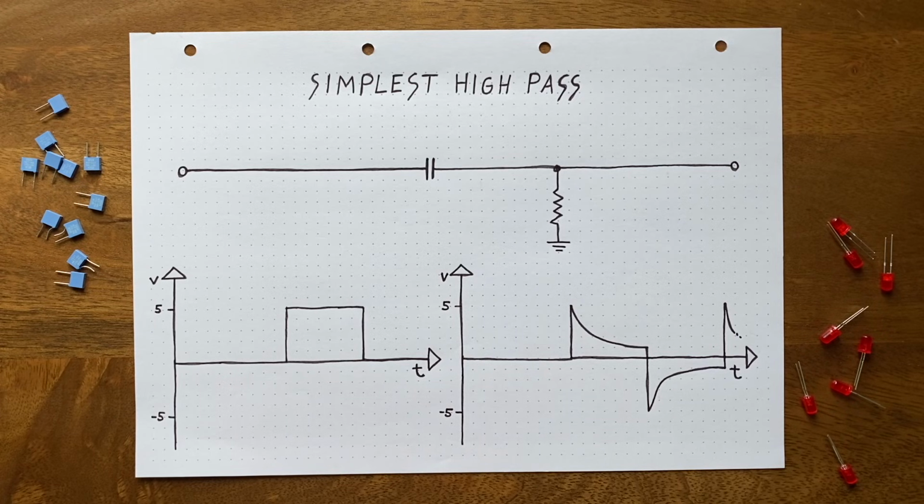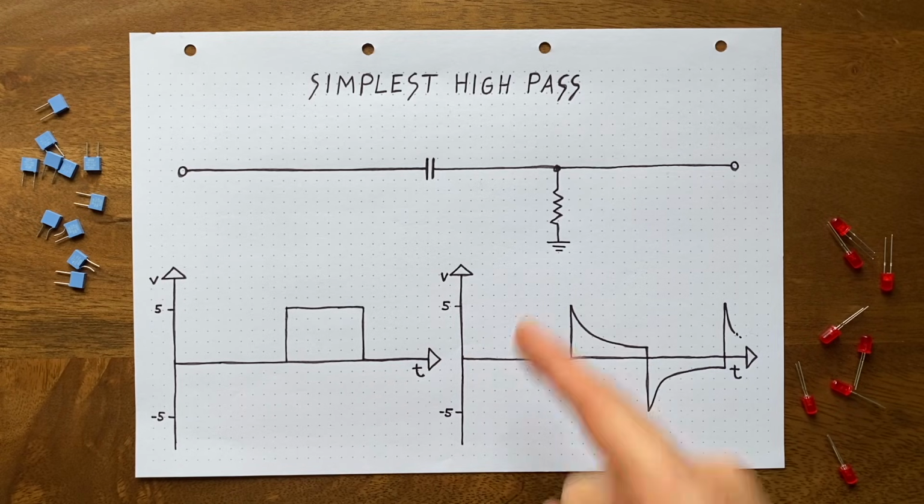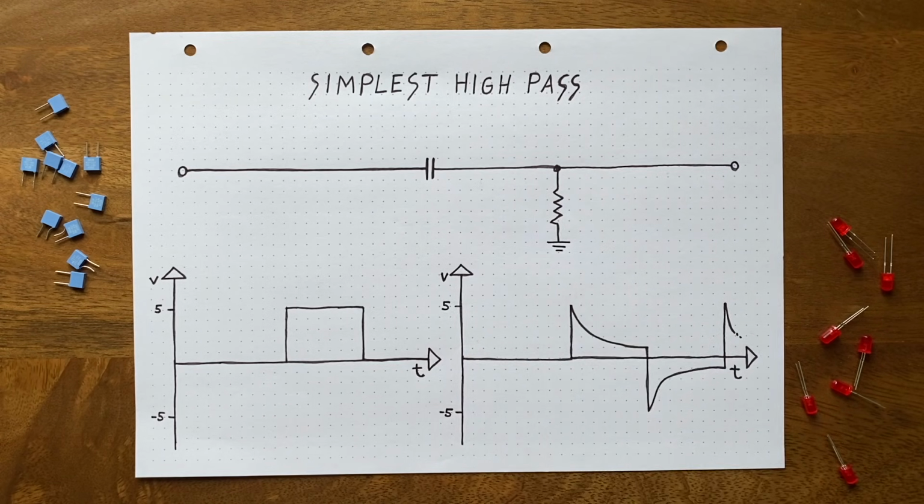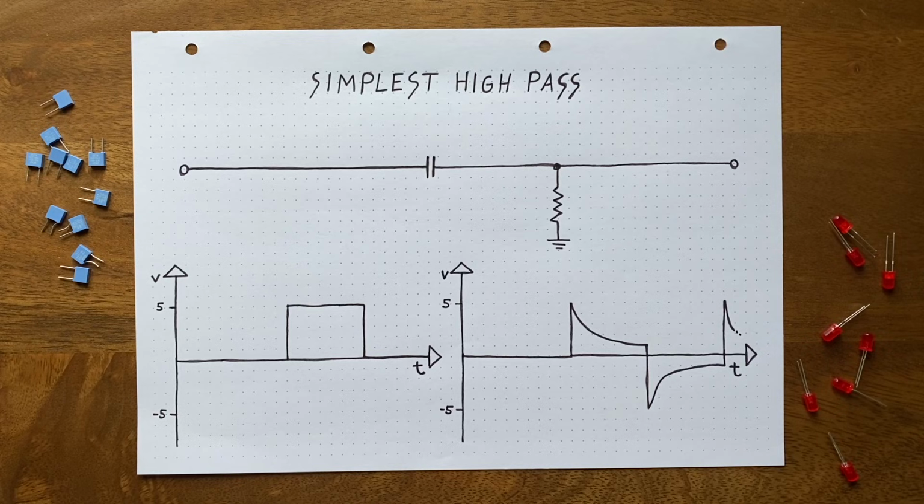can be quite useful. If you've seen my DIY VCO series, you might recognize this as an AC coupling circuit, the only difference being larger and fixed values for the components. But back to our filter. The end result is a wave that's decidedly more spiky than the square we sent in, which, like I said before, means that we've effectively killed a lot of the low end. Audibly, we should get a more nasal sound.